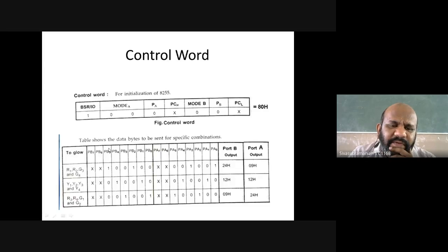So that's why we are given it as don't care case here, right? So port C lower as well as port C higher or port C upper are don't care cases. Even in port A and port B, the last 6 and 7 pins, right? So these 4 pins are also not being used here, right? It is purely left to our option.